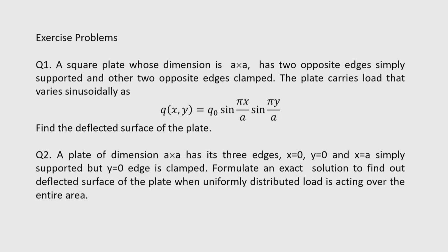Okay. Second question: we will see a plate of dimension a cross a. This has its three edges, x is equal to 0, y is equal to 0 and x is equal to a, simply supported, but the y is equal to 0 edge is clamped and the other edge y is equal to b edge is also clamped. So, let us formulate an exact solution using the Levy's method to find out the deflected surface of the plate when there is uniformly distributed load acting on the entire area.